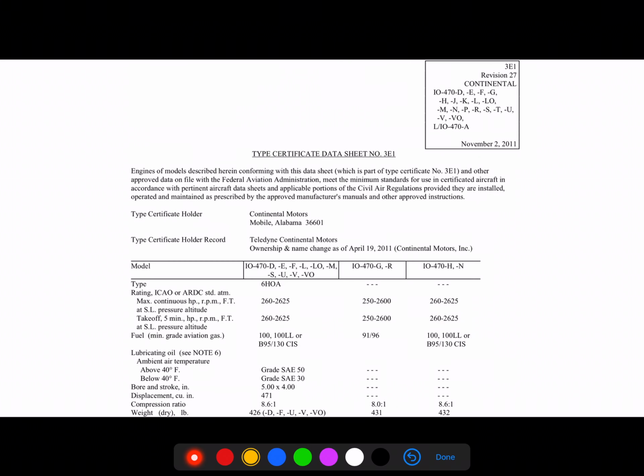One of the issues we run into with manuals is that once a manual is printed, it is very rare to see a complete reprint of a maintenance manual. Typically, we get revisions, and those revisions are added in. So if a manual is updated, then the manufacturer will make available the revision pages, and you'll get a sheet and a whole bunch of pages that say, replace pages 10-20-2 with the newest version. And we stick those into the manual as updated information.